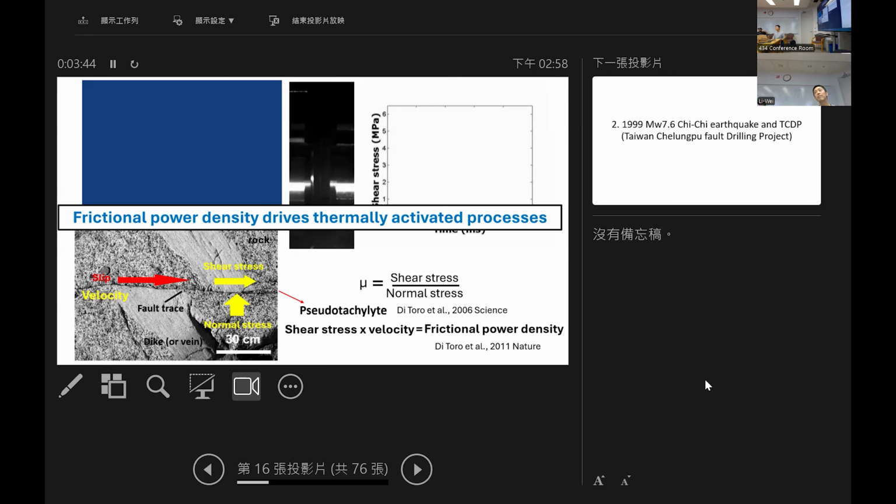If flash heating is driven by asperities, you can artificially make the rate. So the radius of curvature is driving it, in some sense. You can artificially roughen your rock samples, and take a differential: something with a very high radius of curvature, something with a very low radius of curvature. Even if you can't measure the temperature, your response will scale according to your radius of curvature. Ah, okay. But that's still an experimental approach. Yes, because if it dissipates very fast, unless you use some other technique, it'd be very difficult.